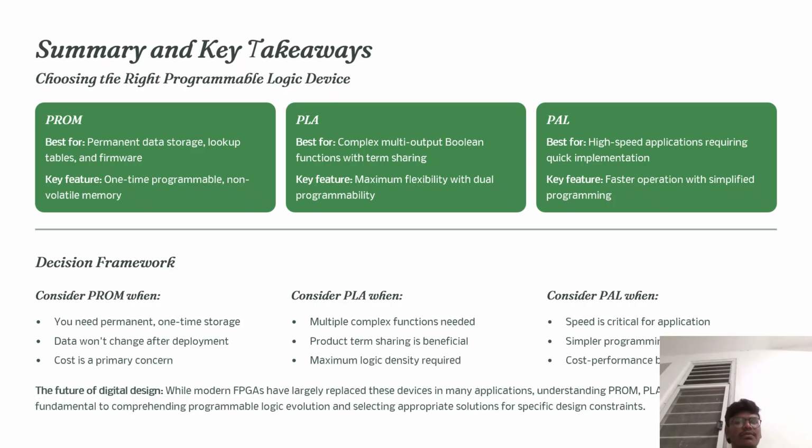Framework. Consider PROM when you need permanent one-time storage, data will not change after deployment, and cost is a primary concern. Consider PLA when multiple complex functions are needed, term sharing is beneficial, and maximum logic density is required. Consider PAL when speed is critical for applications, simple programmability, and cost performance is best.